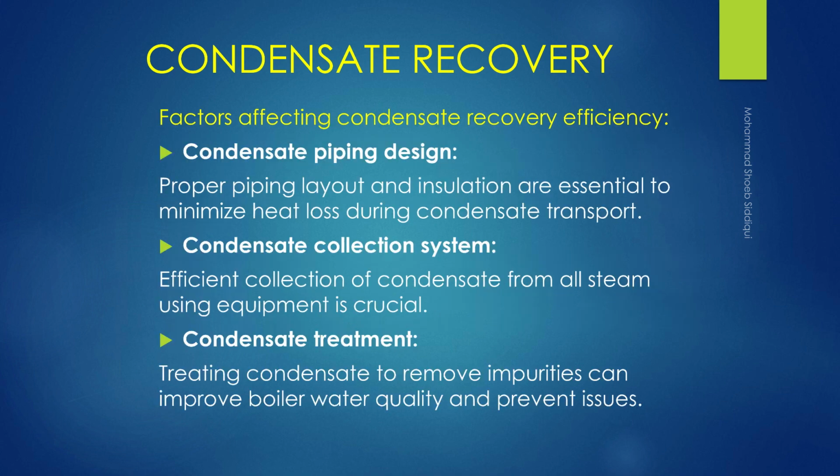Factors affecting condensate recovery efficiency. Condensate piping design. Proper piping layout and insulation are essential to minimize heat loss during condensate transport. Condensate collection system. Efficient collection of condensate from all steam-using equipment is crucial. Condensate treatment. Treating condensate to remove impurities can improve boiler water quality and prevent issues.